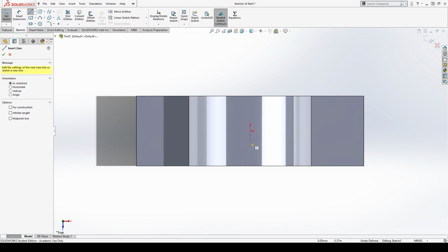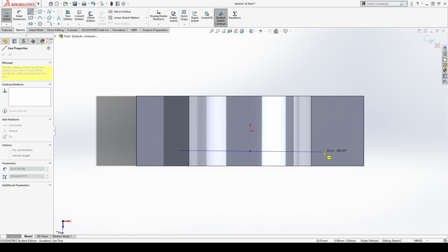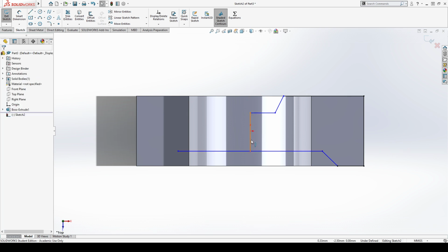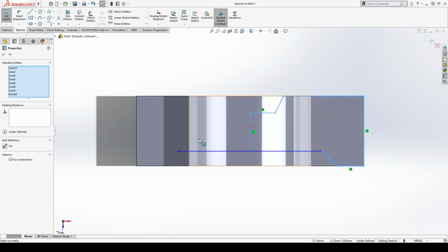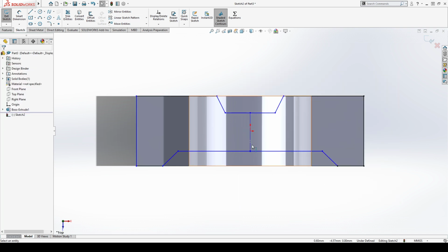It's probably some really wacky constraints that I have. It has to pass around some stuff. So I'm just going to do that there. Just going to have to pass around there. Go back. There's different constraints on this side. Then I'll stop that there. Drop down a construction line. Mirror those over. See, because I just selected one construction line there and everything else is normal geometry, it mirrored it all over just by default by picking that construction line.